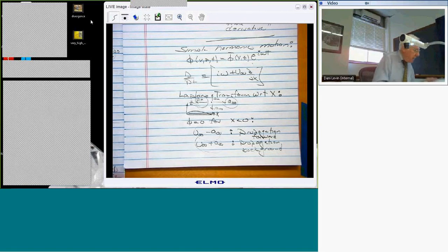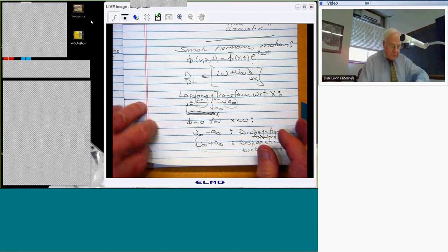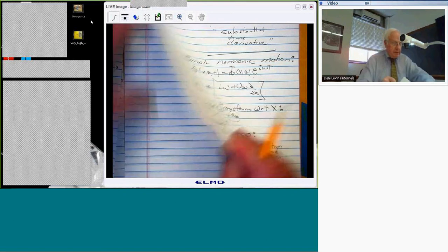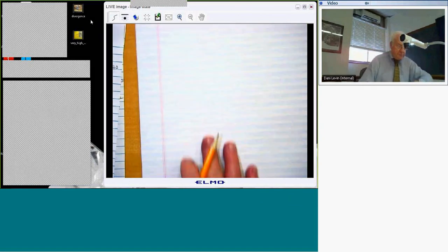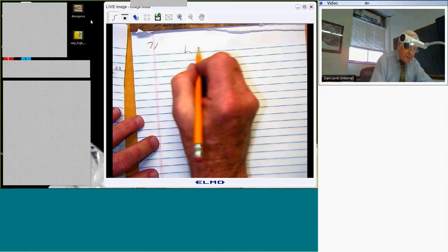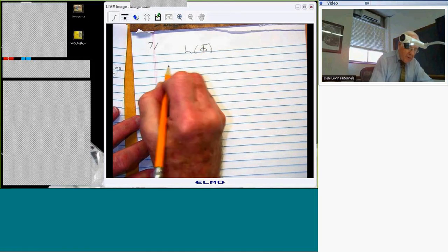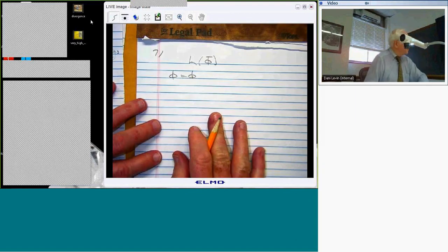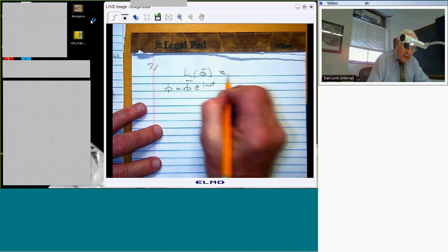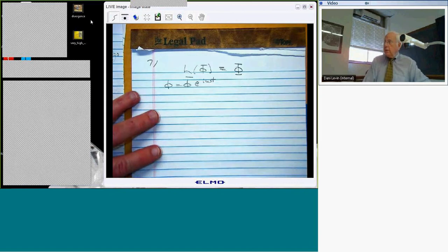Okay. So, because of this, nothing's happening ahead of the airflow. So, nothing's happening for x less than 0. So, taking the Laplace transform with respect to x is an okay thing to do. I hope you agree with that. So, let's do that. We're going to take a Laplace transform of phi bar. Remember, phi is phi bar e to the i omega t. And I'm going to call that capital phi because that's what I call it in the book. It'll be easier for you to read the book when I do that.